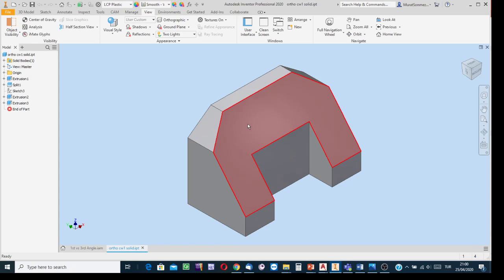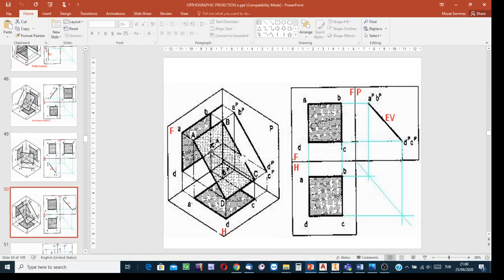So, since the profile side of the object is parallel to the profile picture plane, this means that surface is perpendicular to the profile picture plane. So while we observe the surface, sending the rays of sight orthographically with respect to the profile picture plane, we see the projection of that surface in the form of such an inclined line.